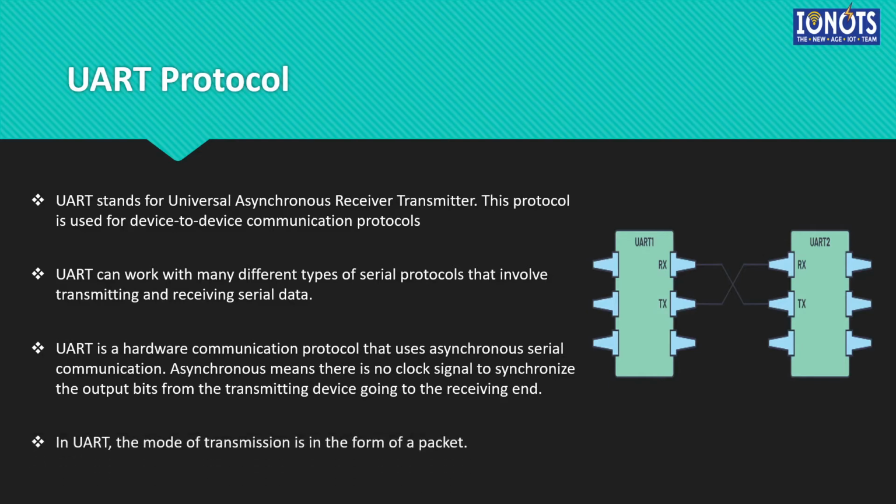In UART, the mode of transmission is in the form of a packet. So, what is happening? Since there is no synchronizing clock over here, the devices, that is UART device 1 and UART device 2, have to independently work on synchronizing the data. UART asynchronous means that since there is no clock signal, synchronizing comes down to the individual capability, which I already mentioned.